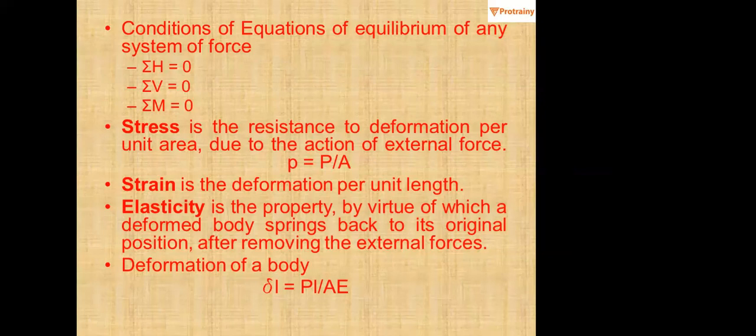So that is elasticity. Then deformation of a body: delta l is equal to P into l upon A into E. So P upon A is stress, so stress into l upon E, that is the deformation of a body.